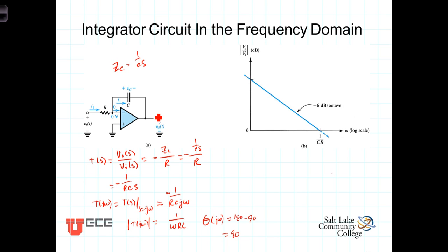We're going to address that in the next video, when we'll add a resistor in parallel with the capacitor to give us a finite DC gain. But using this transfer function, let's just look at the Bode plot. It falls off as 1 over omega. As we've seen in our previous discussion of Bode plots, falling off as 1 over omega corresponds to a straight line